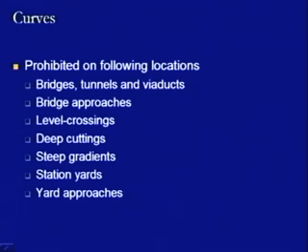Even in the case of yard approaches, where trains are either moving into the yard or wagons are coming out of the yard, as the trains have been formed and have to go to the platform for taking up the load, in all such conditions curves should not be provided. Here, sight distance is one of the reasons for the restriction on provision of curves.